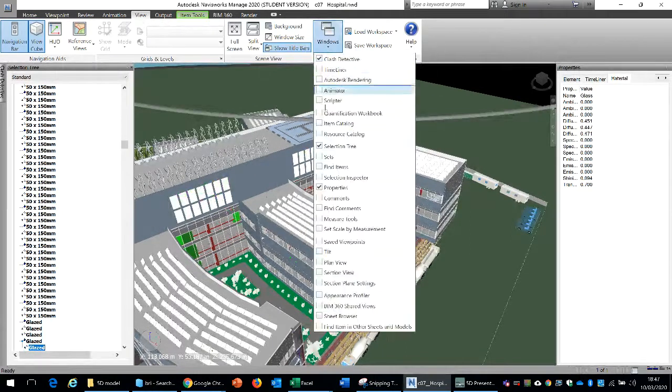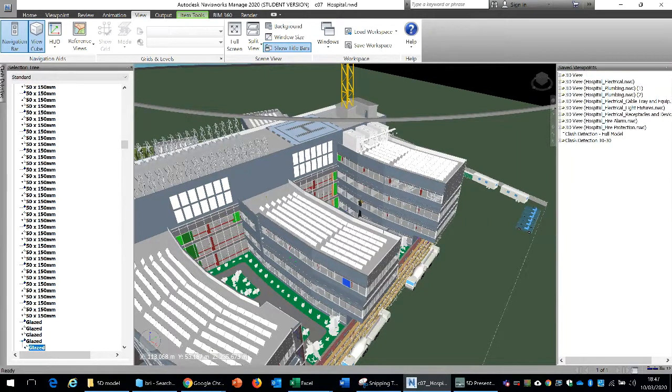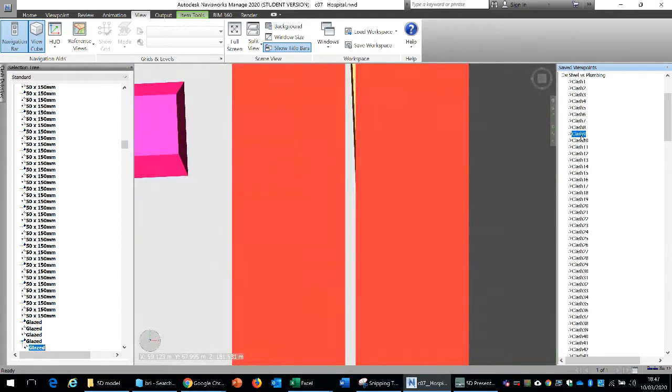So if we just preview maybe a saved viewpoint. Now, a saved viewpoint is essentially a window which allows us to take a snapshot or a perspective of a model from different dimensions, right? So here we are given the results of a clash detection between different contractors. So for instance, steel versus plumbing, right? If we look into this folder, we can see that the clash was run between the steel and the plumbing drawings, and we have come up with a number of different cases where there is maybe a physical clash between steel fixings and the plumbing items.